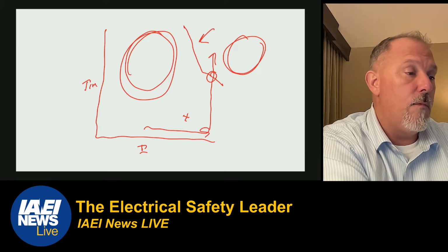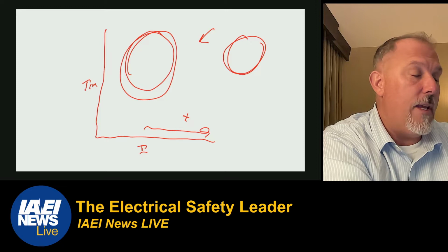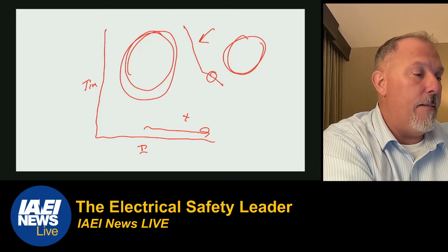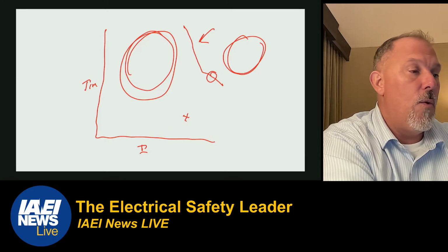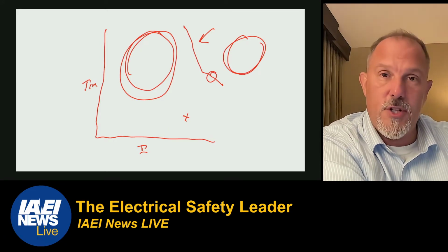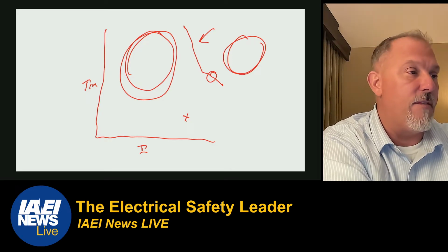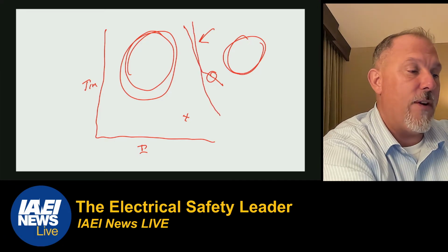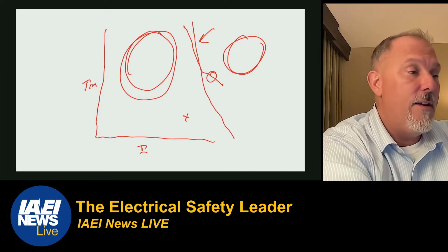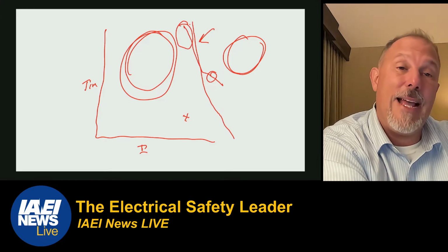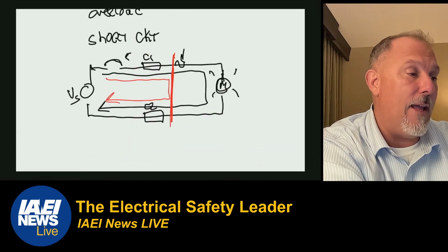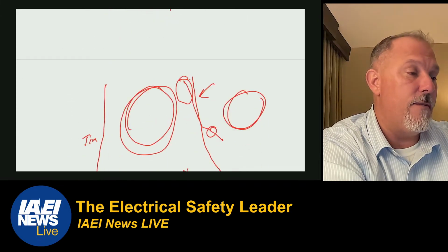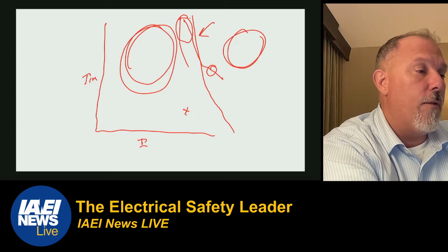So what we do is, if I'm going to provide short circuit protection with the primary overcurrent protective device, if your overcurrent protective device cuts into that transformer curve, that's okay. You might say this is not being protected, but it's actually going to be protected by this secondary overcurrent protective device, which will be plotted over this area here.